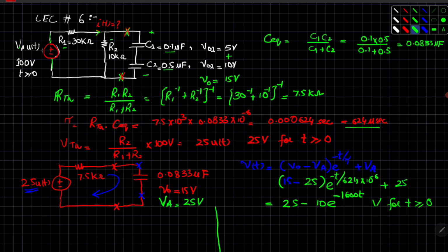If we plot this equation, this is the time axis in seconds. Here this will be our initial voltage, which is of course 15 volts, and this is our Va, our source voltage. If we plot this curve, the capacitor will start charging from this point. This is the dotted line, and at that point we have 5 tau. We consider that up to this point our capacitor will be fully charged, so starting from this point and ending at this point, the curve will be like this. So this is the graph of our equation.